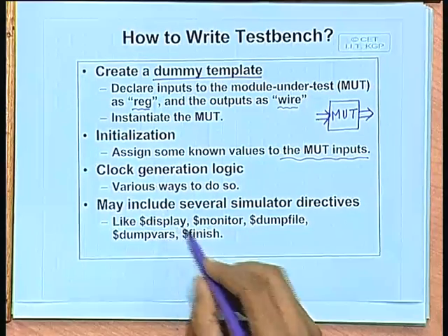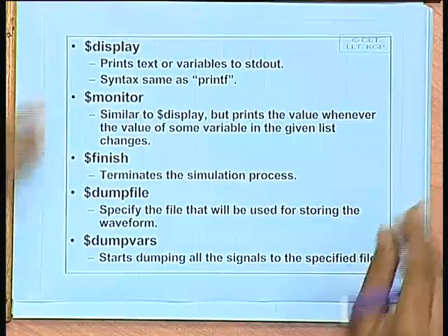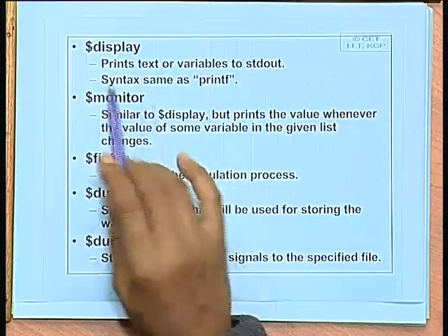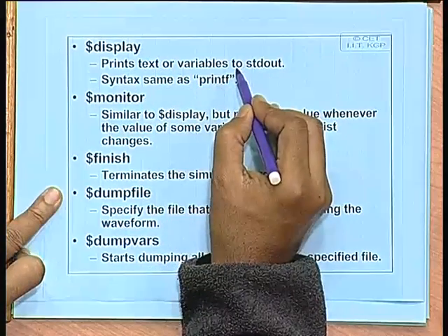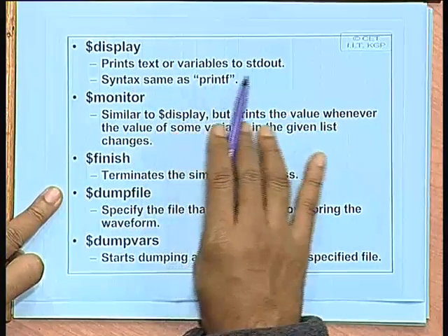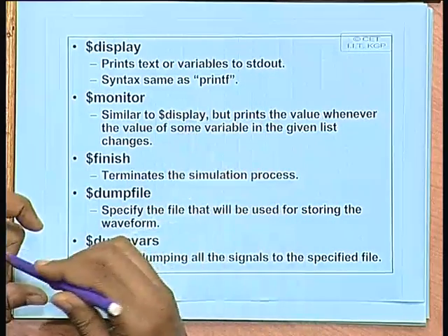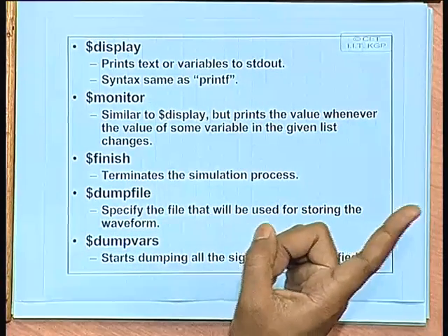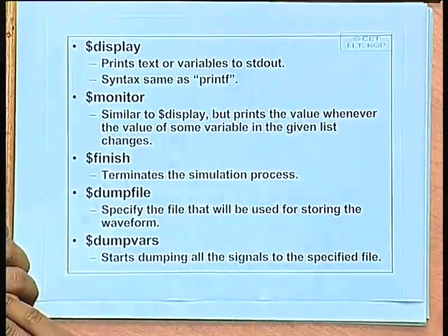Display is just like a print statement. Whatever you give as an argument to display will be printed on the standard output, which is the screen. So whenever you want to output a string or a message at some point in your test bench file, you give a display command, so that whatever you are giving will get displayed.